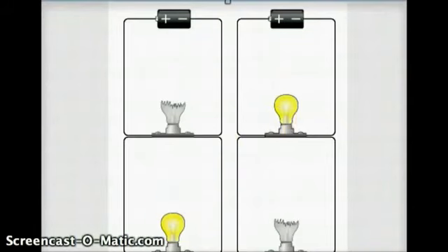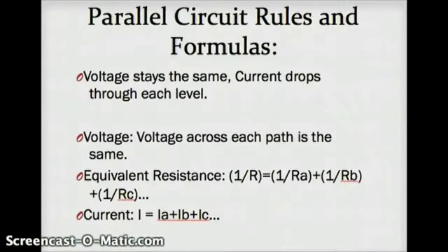And unlike a series circuit, the lamps stay bright if you add more lamps in parallel. Parallel circuits are useful if you want everything to work, even if one component has failed. This is why our homes are wired with parallel circuits. Here are some things to know about parallel circuits. Unlike in series circuits, the voltage level stays the same throughout. However, the current will decrease throughout the branches. These formulas will also be helpful to find the answers to certain word problems involving parallel circuits.